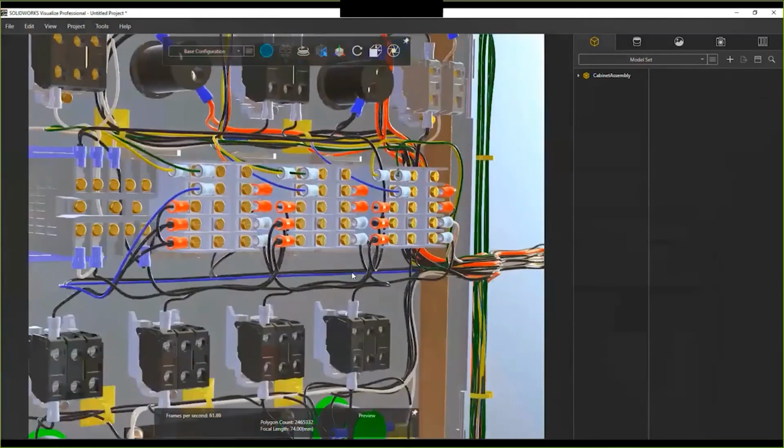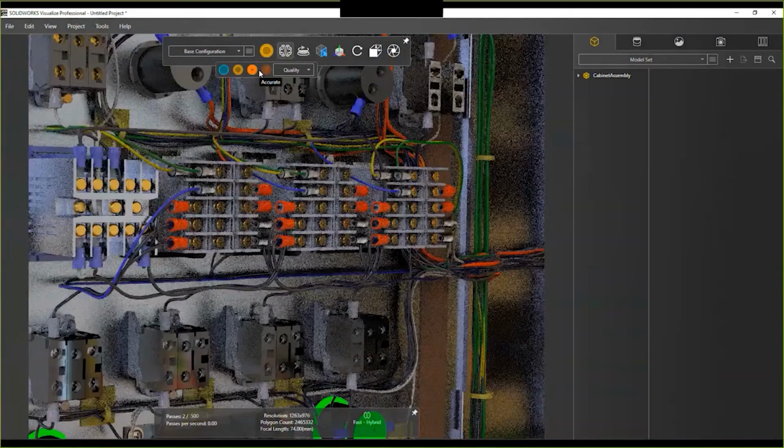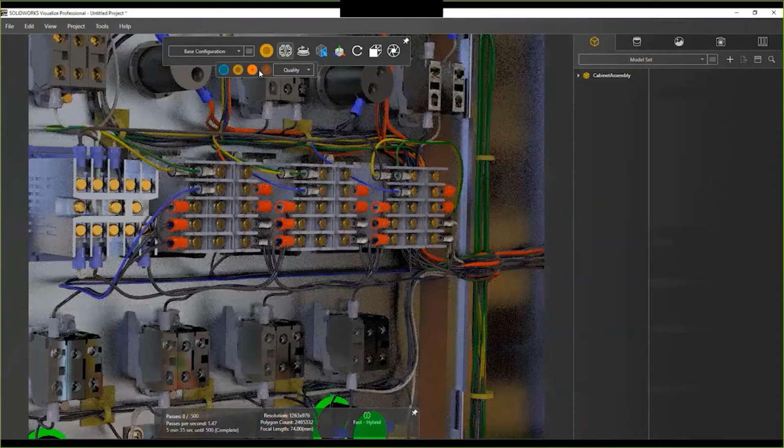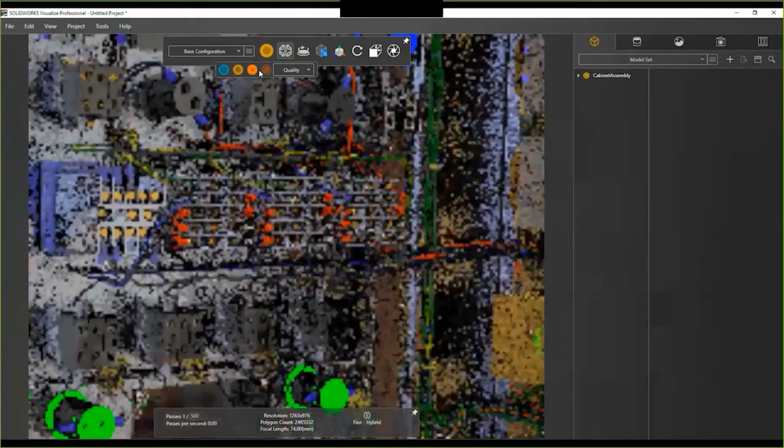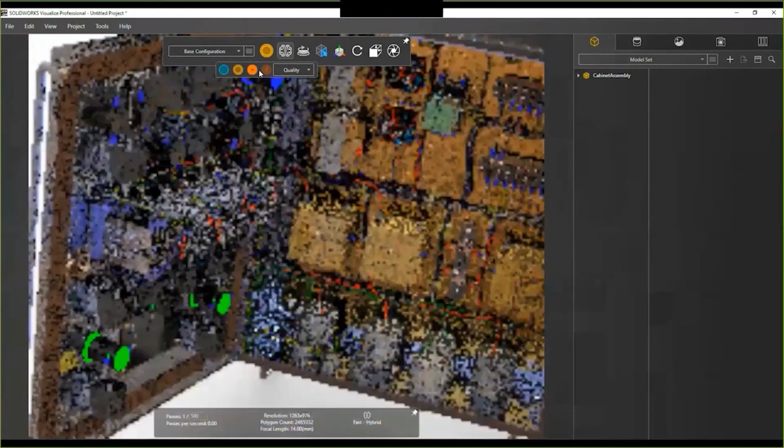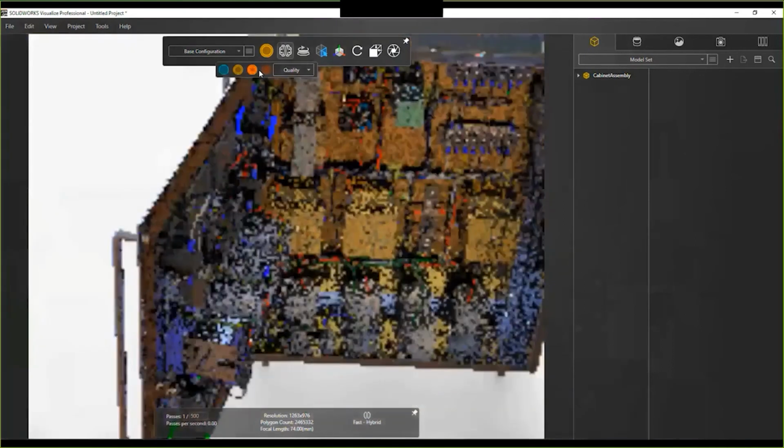And what we're looking at right now is in a basic mode. Basic is when you're kind of starting to apply materials, appearances, and change things a lot. But when I turn it on to either fast or accurate mode, that's when it starts to do the ray tracing. The ray tracing is just me beginning to actually render out what these materials and appearances look like, have the light begin to scatter, reflect, and refract depending on the material I have.